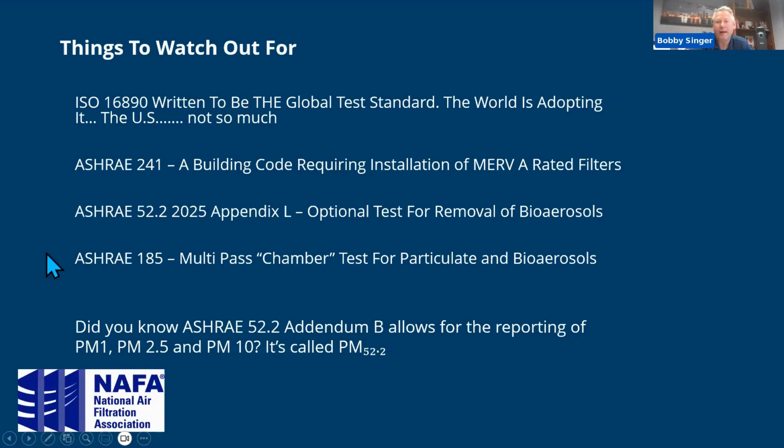There's also an ASHRAE 185 that is a multi-pass chamber test for particulates and bioaerosols. The idea is a more realistic test. It's, as I mentioned, a multi-pass. So you're testing within a space as opposed to just before and after a single pass through a filter.